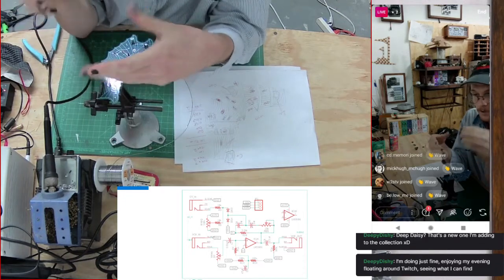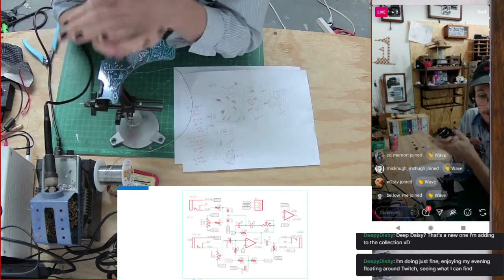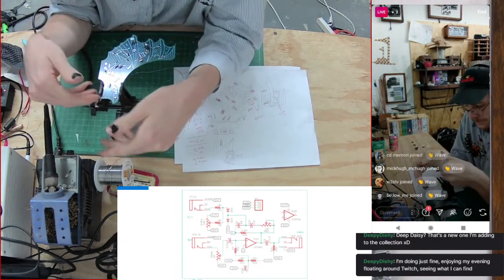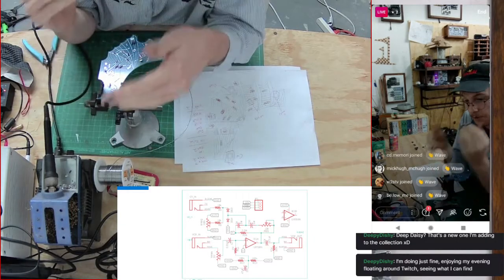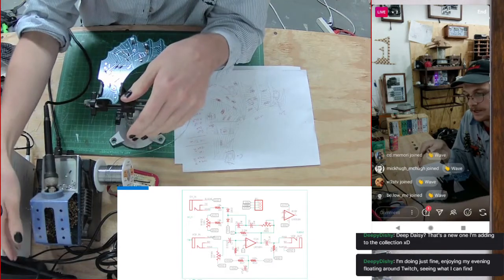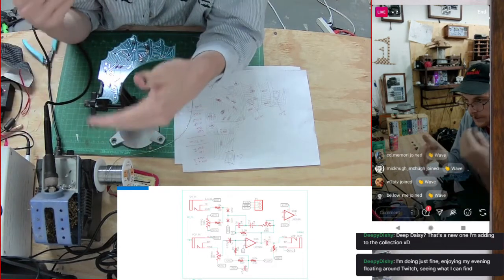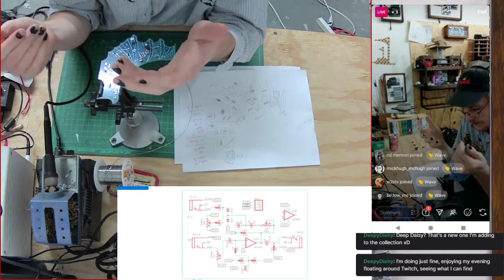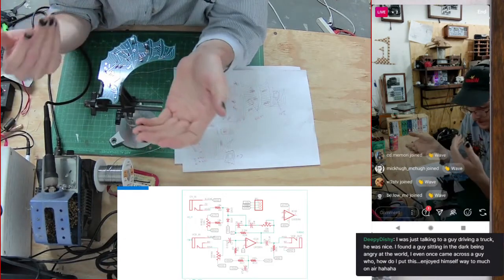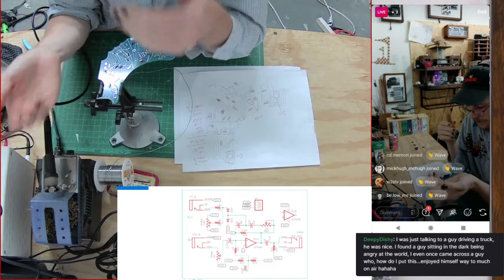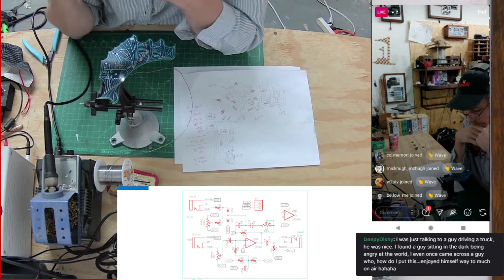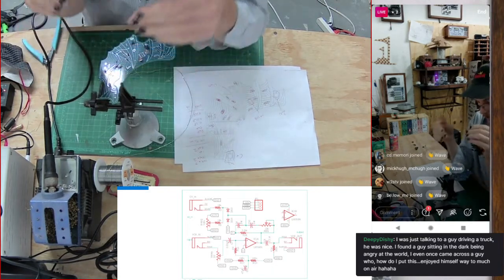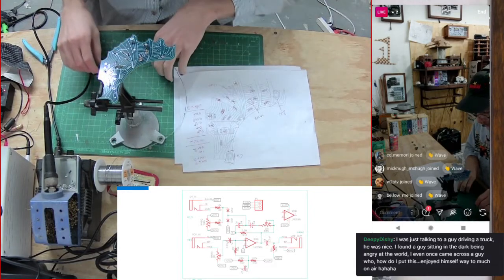3 jacks. One jack is going to be for inserting whatever sound source. In our case, it's either going to be noise, if we want to filter noise, which has a really nice effect. Noise that goes through a low-pass filter tends to sound like wind outside of your home, or waves on a beach or something. It's very nice. Or an oscillator of any shape or size: a square wave, triangle, pulse, saw. We're going to be putting in a sine, or a triangle and a square wave, because that's what I have on one of these boards over here.